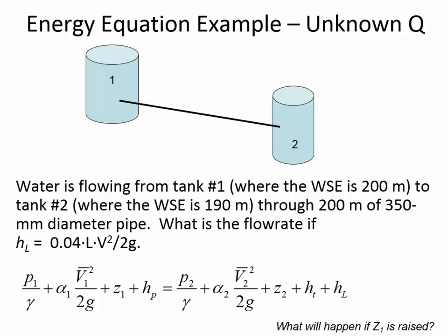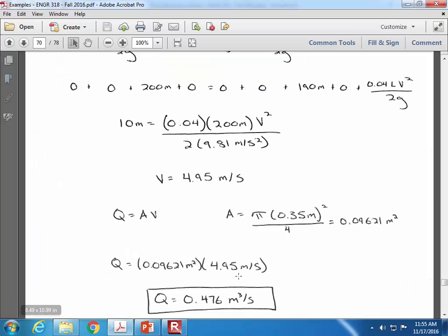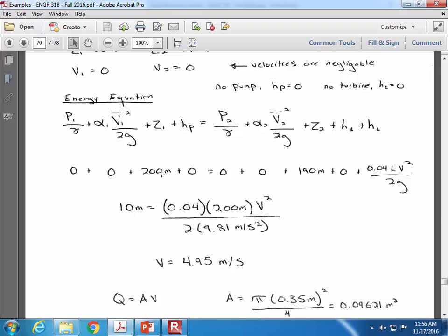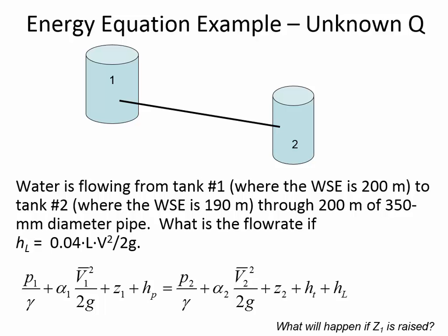So the same amount of energy makes the fluid move more easily. So here, if you make the straw bigger, the fluid can flow more easily. So you'd increase the velocity, you'd increase the flow rate for the same driving force, because we're spending the driving force on head loss. All of this cancels out, in the solution, to, in this equation, the difference in Z is equal to the head loss. And so the elevation difference all goes into head loss, and the head loss has the length of pipe parameter, the velocity parameter, and so if we make the pipe diameter larger, then that would increase the flow. We'll get into a lot more about the driving force as we look at additional examples.